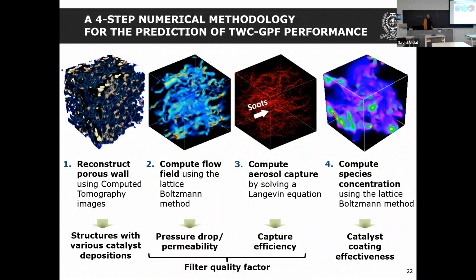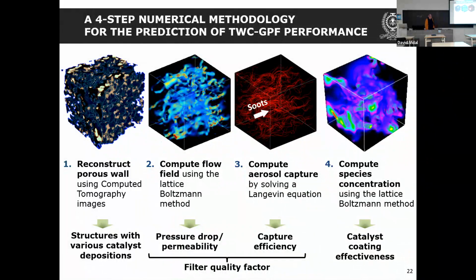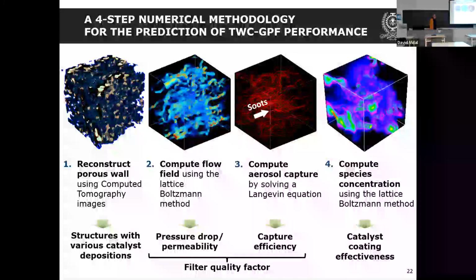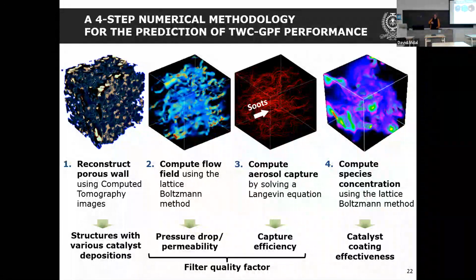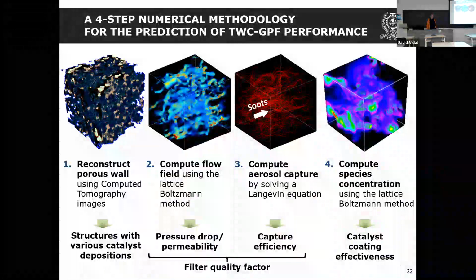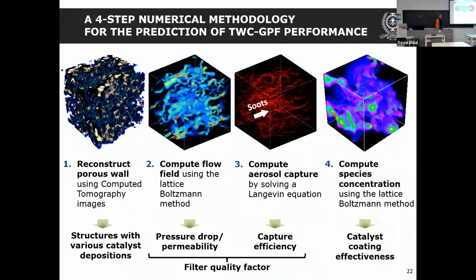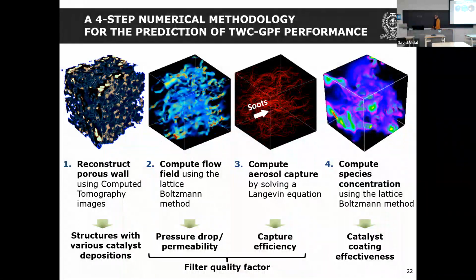You need to convert eventually the noxious gas, and you want eventually to compute the species concentration field that is transported through the porous wall and eventually diffusing and reacting at the catalytic phase. Okay. So from those simulations, we wanted to get as information the catalytic coating effectiveness.